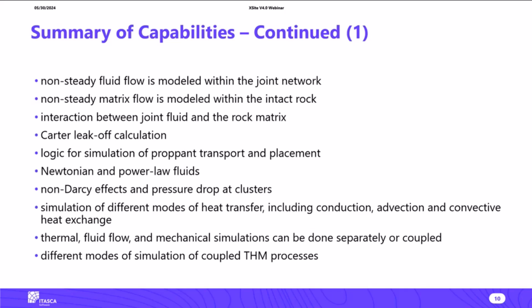The fluid flow also includes the capability to simulate proppant transport and placement. The fluid in the code can be Newtonian, but we can also represent power law fluids. We can also represent non-Darcy effects and pressure drops in the clusters.